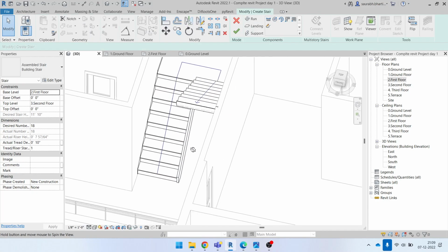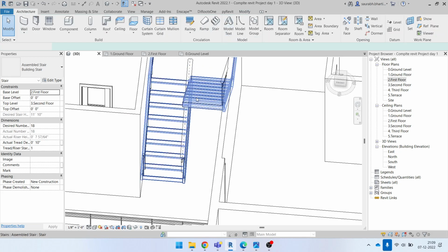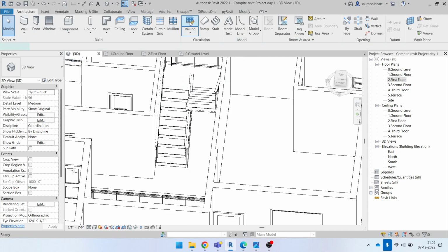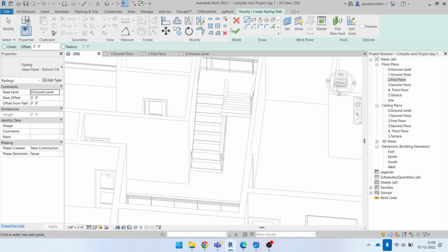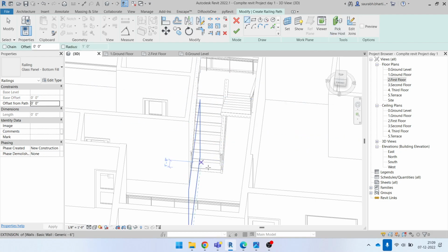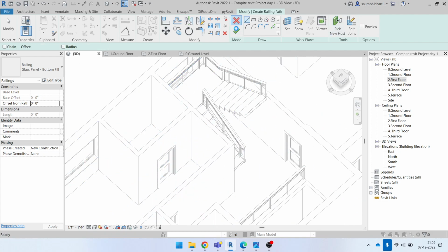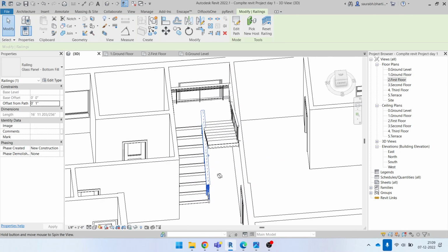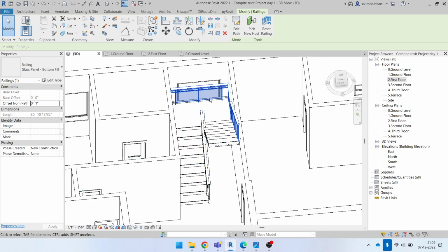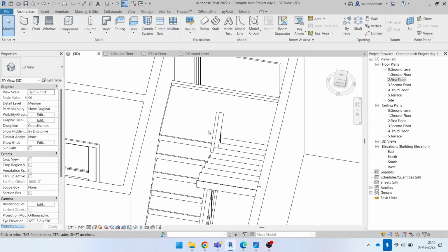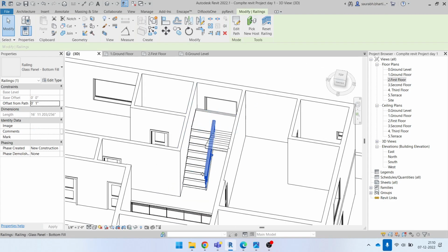Then if you want to put the railing back again, let's just go to edit stair, and okay, the railing is not editable here. Let's just select the railing. So I'm going to railing, and in railing I will try to pick a host, pick this as a host. Okay, just a second, let me see why the railing is making error. Okay, we don't want the glass panel on the sides, we just want it on this side. So what I'm going to do is select the side railing and delete it first of all, and let's just keep it without railing for now.